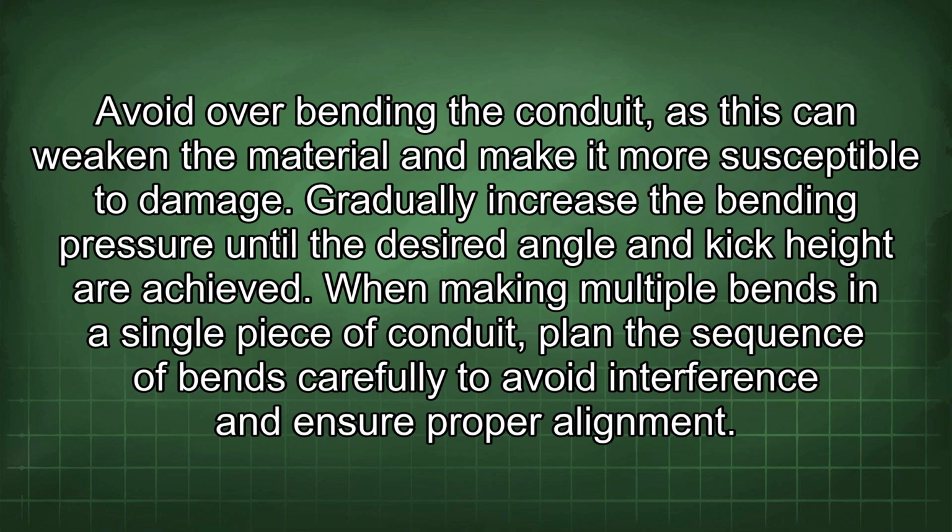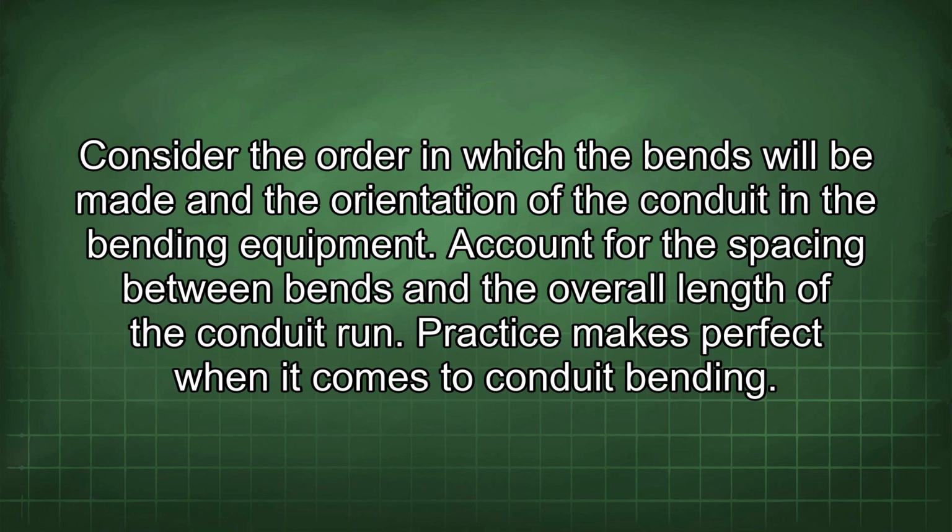When making multiple bends in a single piece of conduit, plan the sequence of bends carefully to avoid interference and ensure proper alignment. Consider the order in which the bends will be made and the orientation of the conduit in the bending equipment. Account for the spacing between bends and the overall length of the conduit run.